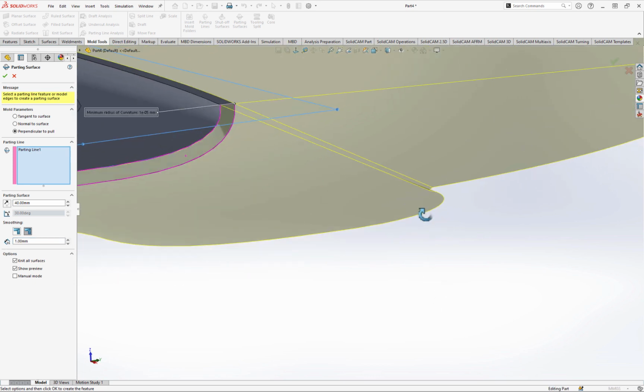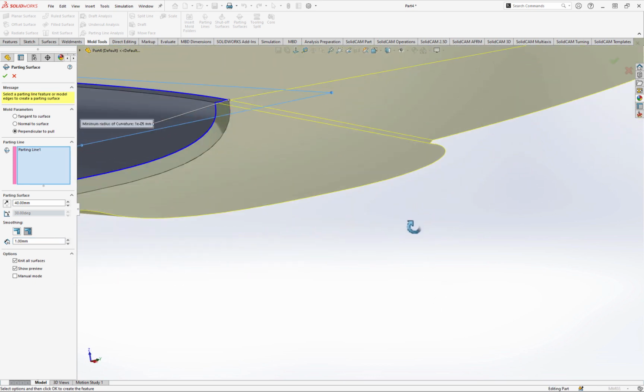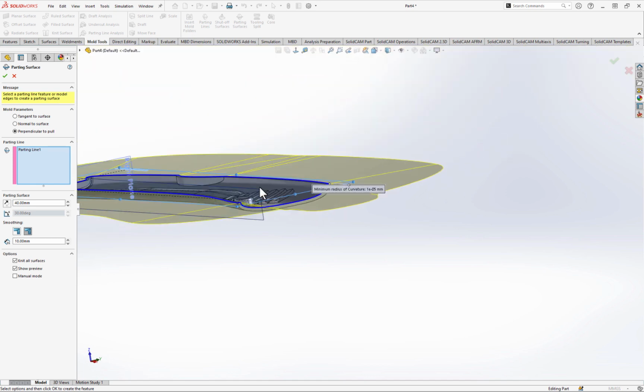And that, with an overhang there, would be very difficult or, more likely, impossible to machine. It has that tight sort of overhang there. So this is why I had to play with some of these settings to try and get something that's a little bit more achievable using our machining techniques that we're going to use later to machine these mould halves.